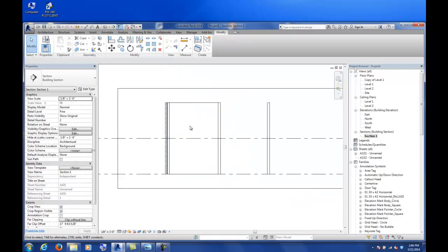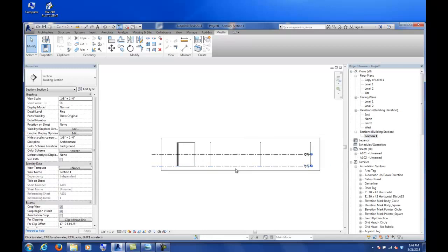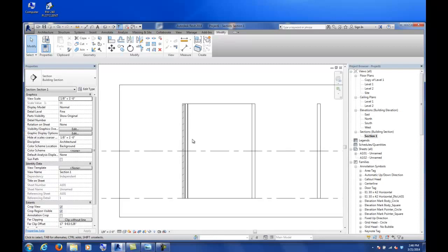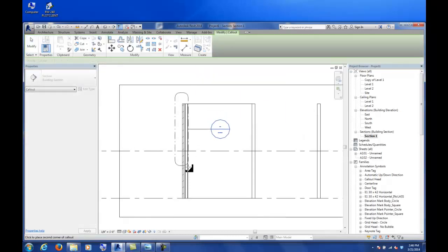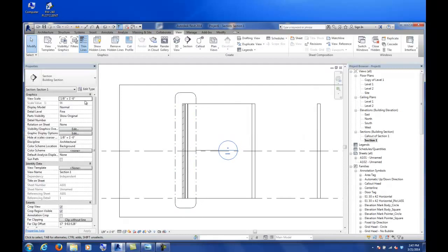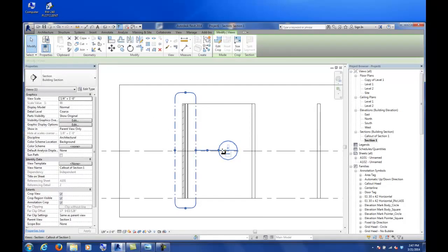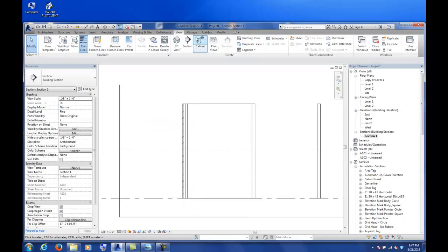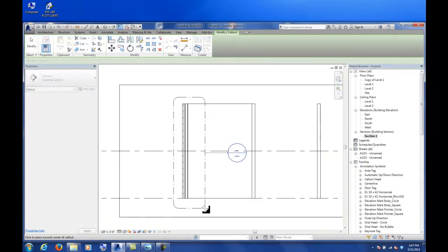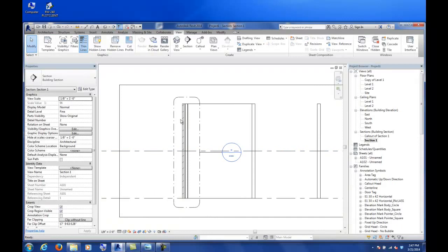But if you wanted this to be a wall section, typically what I normally do is you have an overall section that shows the overall building. And then a lot of times what you would see in construction documents is you'd go to view, and there's another view type called a call out. And you can draw this kind of window, and it's kind of like this blow up detail that would go around whatever you're trying to eventually blow up to another scale. So to go over that again, I went to view, call out, and then you can do that. And it'll make a box.